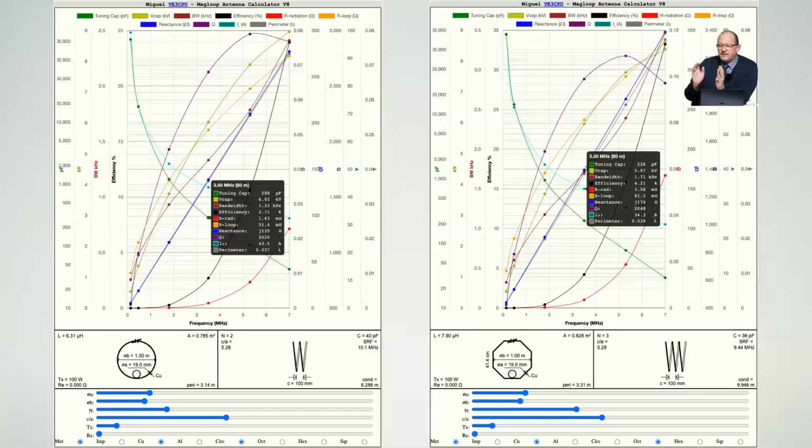And that happens because you get quite a bit of capacitance between the coils, or you get quite a high amount of inductance, sorry. And as you get the coils further away, so if you change the spacing ratio, you'll notice that SRF can then move up. On the right, you can actually calculate also different shapes of antennas. So there's one for an octagon.